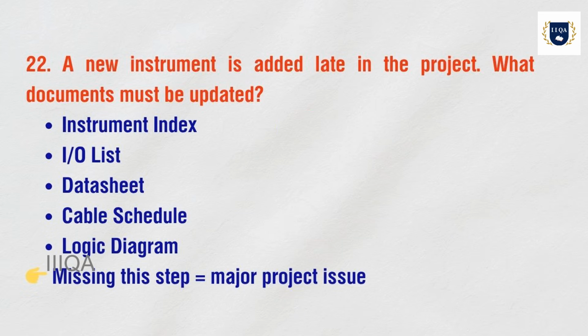A new instrument is added late in the project. What documents must be updated? Instrument index, I/O list, datasheet, cable schedule, logic diagram. Missing this step is equal to a major project issue.